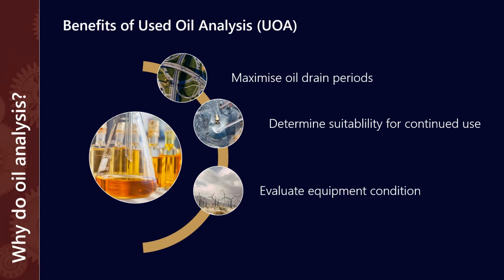We can evaluate equipment condition. So is my equipment operating in the way that I would expect? And we can also do some troubleshooting. So that can be both in real time and post a failure event. We can use used oil analysis data as part of our investigation.